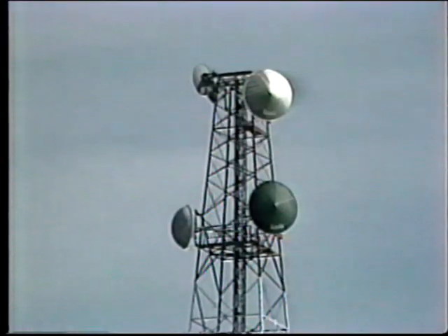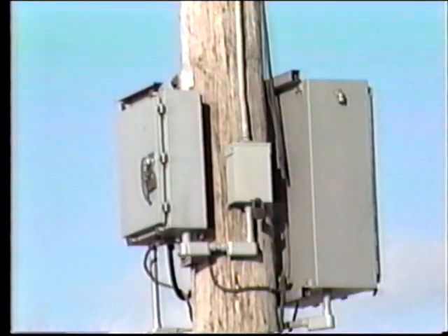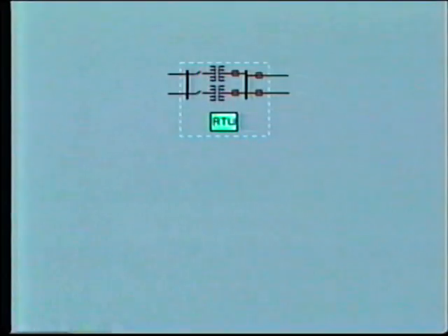In fact, it is only with the development of modern communication methods that SCADA has become feasible. The data is first collected by remote terminal units, known as RTUs, which are located in substations throughout the system. In some cases, small RTUs may be mounted on distribution poles in isolated areas. The RTU is essentially a microprocessor which can store and process data in digital form.